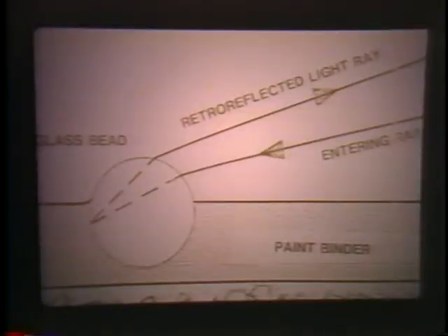Nighttime visibility is dependent on reflectorization. Reflectorization is achieved by adding glass spheres or beads to the surface of pavement marking material or to the material itself. The glass spheres are the retroreflective devices. Usually, the pavement marking material film is very thin, and the glass beads must be exposed to be effective. So many glass beads are lost through tire wear long before the marking is worn away. When reflectivity is gone, the marking must be replaced.